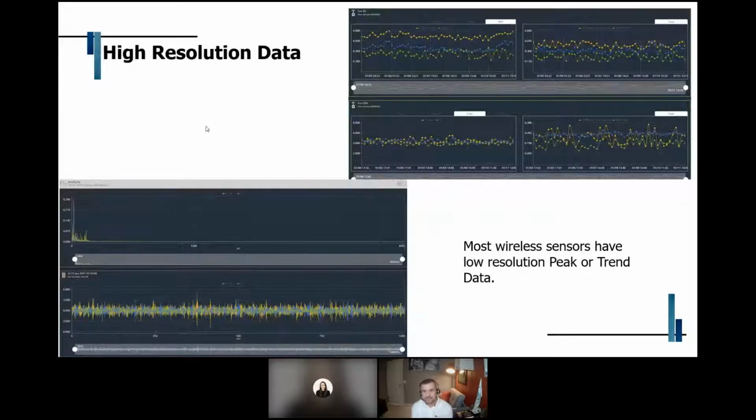You will want to be able to see your trend data. So if you're not a vibration analyst, it's easy to understand that up is bad, flat is typically okay. And it's also going to give you a multitude of information from your peak vibration on all 3 axes. Also, monitors temperature as well. There's other solutions that might monitor amperage or runtime, things like that.